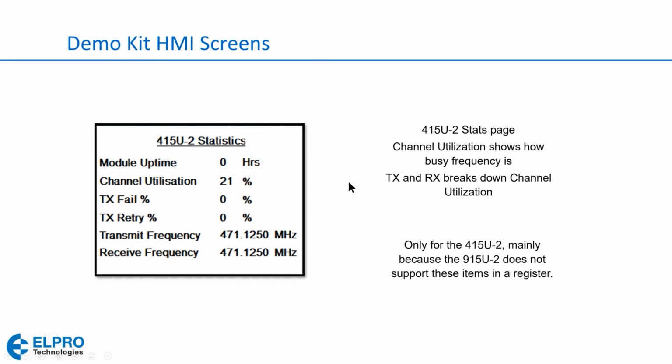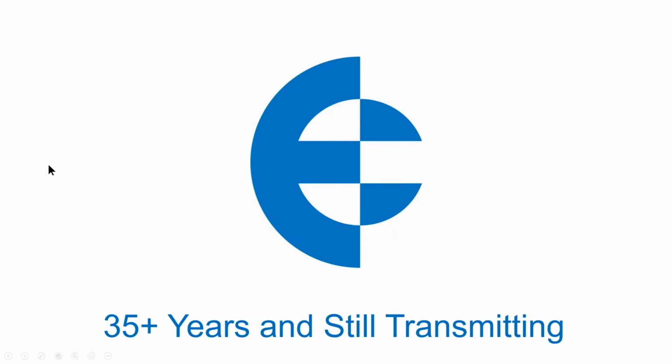So that's pretty much it for today. Just in quick summary, to test a radio link, there are 2 methods. You can have a Pathloss software survey, and the second method is on-site with the hardware. When you're on-site, make sure you document what antennas you use, what the RSSI was at each remote site, and where the antennas need to be mounted.